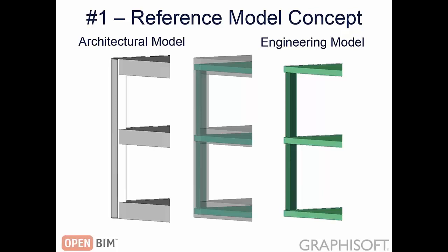Of course, sometimes there can be some design mistakes, where there are real conflicts between the models, but it can also be that the practices in the industry are different. For example, the architect can be modeling with nominal measures, and the engineers are using the actual measures, so that they can be slightly different sizes. And again, it's something that we have to agree on at the project level. What are the ways of modeling? What is the correct level and correct accuracy of the models?